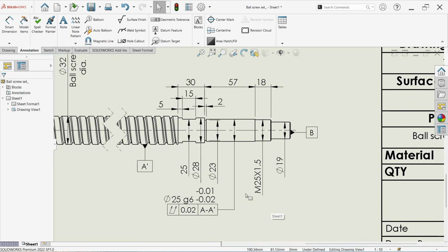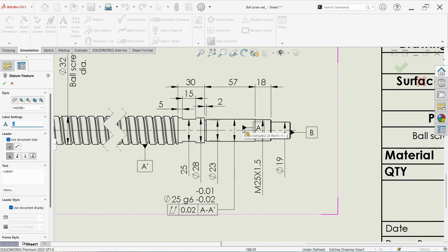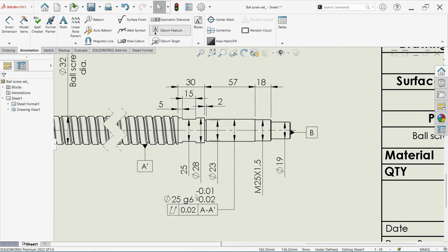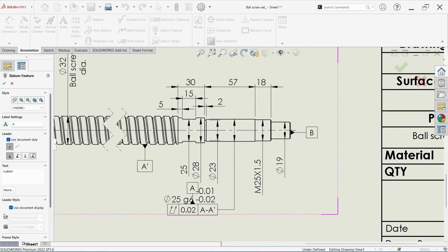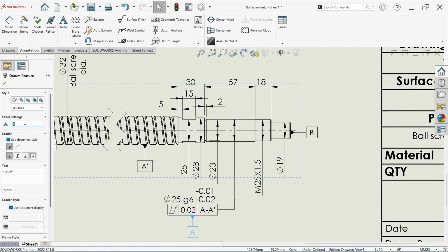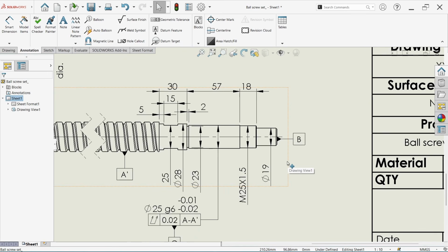So we also have to define this bearing step as a datum. To define it, we can attach a datum on this surface, or we can define the datum attached with the dimension of this step. We already have datum B and A, so we can define this as datum C. And here, which control should we define: runout, total runout, or only position?